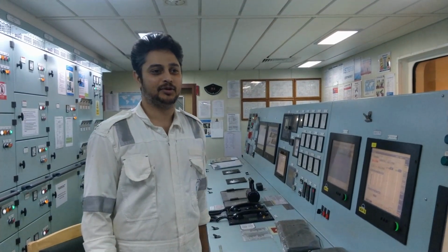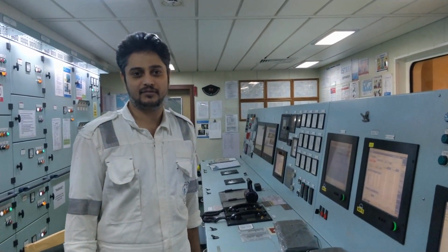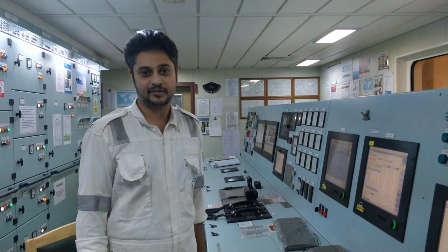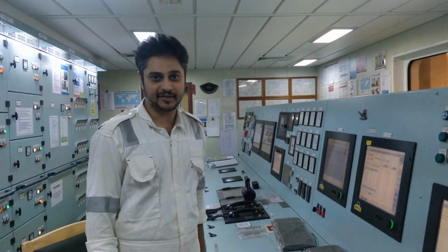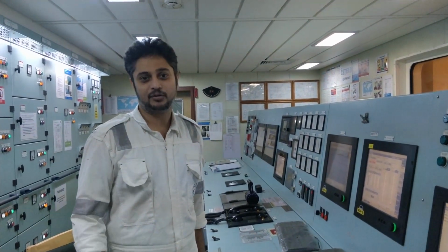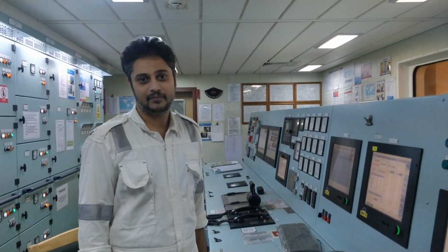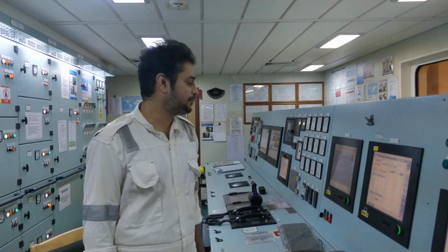In ME engines, at the starting air valve of each and every unit, we have a solenoid valve. So the function of the distributor is actually carried out by the solenoid valve. Whenever the solenoid valve energizes, the pilot air goes inside and activates the starting air valve, thereby admitting the main air. So how is the signal transmission happening?